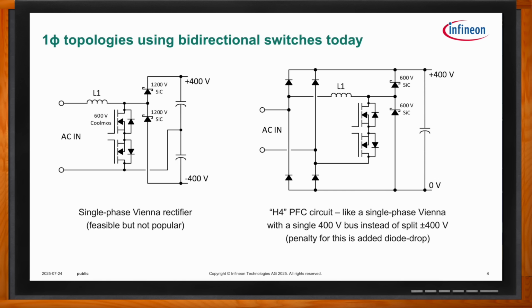One of the nice features of this is that you don't have any worry about shoot through. The switch is either on or off, and there's no way to mess that up. There's no way I can have that switch on and conflicting with another switch that's on. So it's a very simple control strategy.